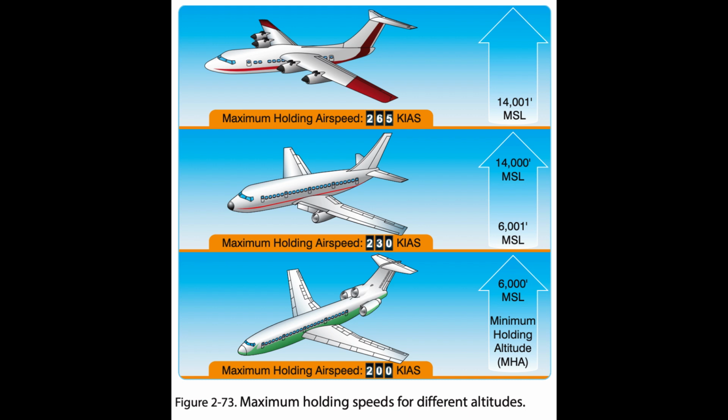En route safety considerations. Fuel state awareness. In order to increase fuel state awareness, pilots are required to monitor the time and fuel remaining during an IFR flight. For example, on a flight scheduled for 1 hour or less, the flight crew may record the time and fuel remaining at the top of climb, TOC, and at one additional waypoint listed in the flight plan.